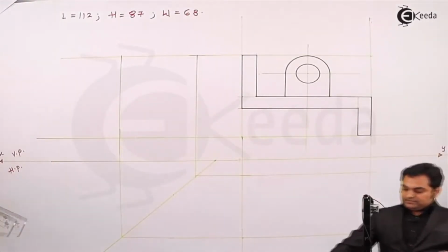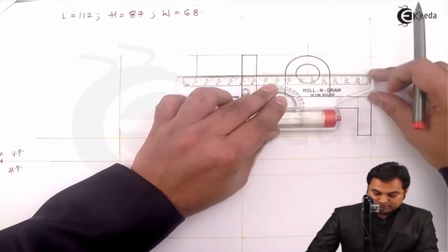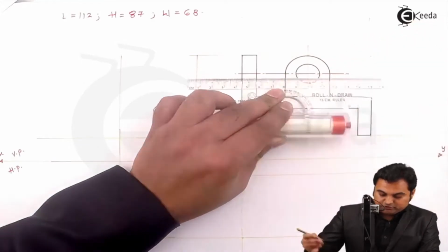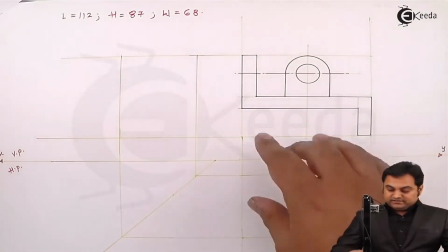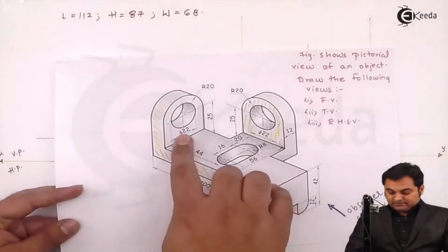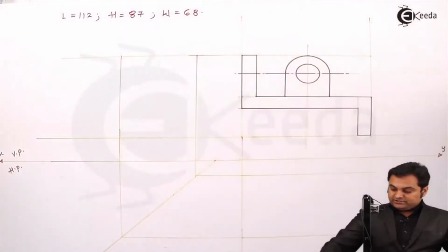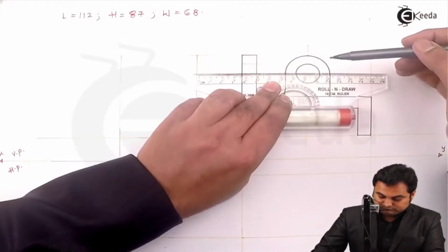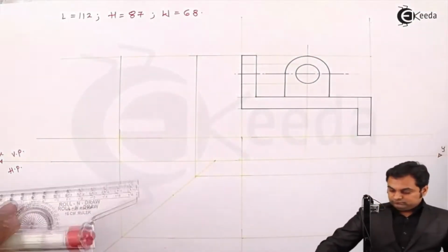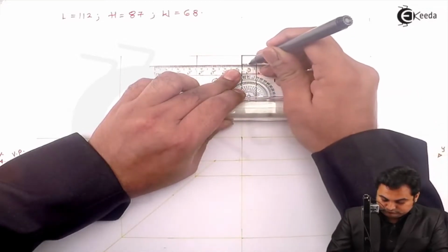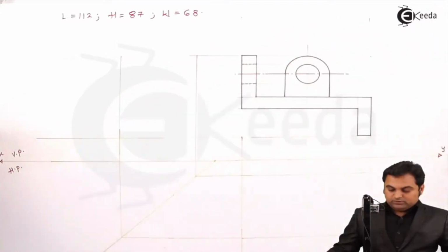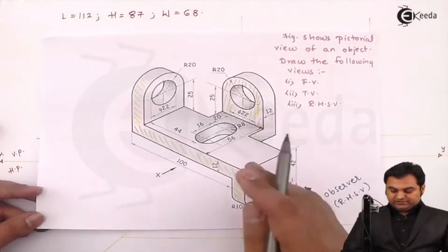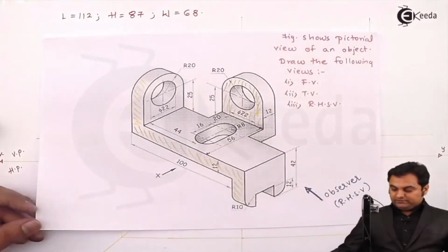So first I'll project the center line, having common centers. Next, inside the semicircle another circle is there having the same diameter 22 mm. So projecting this circle, this is the hidden circle. Next, there is another portion which is hidden, which will not be seen from the front.